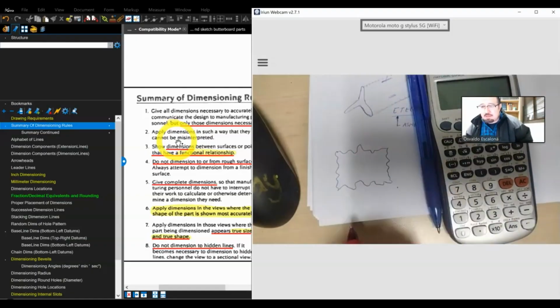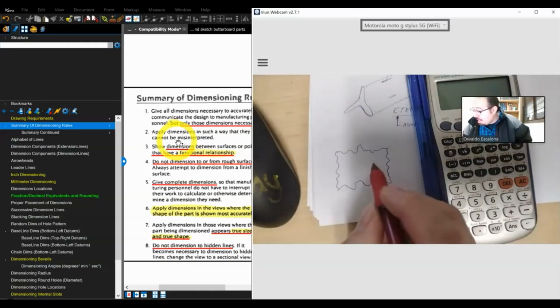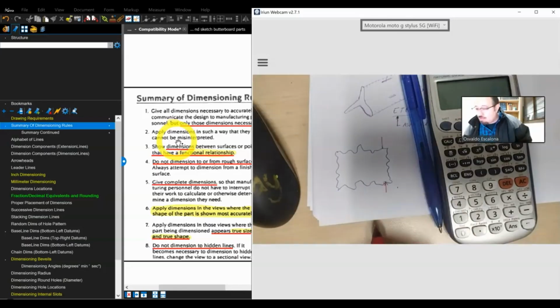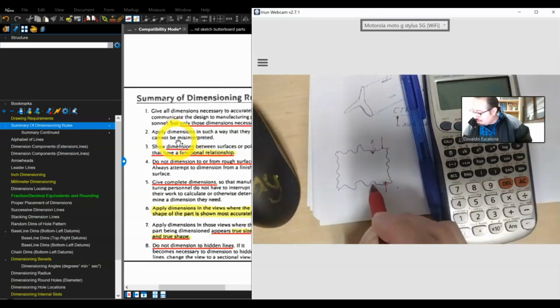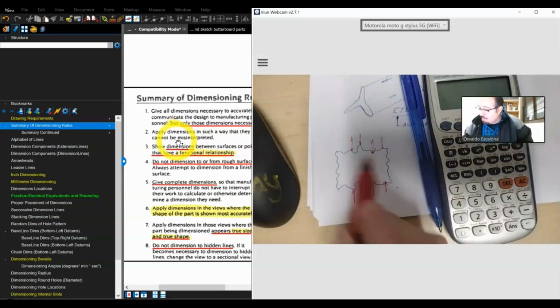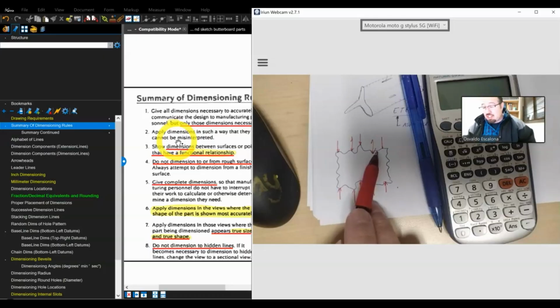And then somebody goes, oh, I'm gonna get a caliper. And again, if you never used a caliper, don't worry, I'll show you how to use calipers later. So they're gonna be like, oh, I wanna measure from here to here. Or maybe I should measure from here to there. Or where do I measure from, right? How do I dimension the height? Because my part is not perfect. It lives in a non-perfect world. The surface finish is different. The machining operation that you do is different. Maybe it has not been machined.